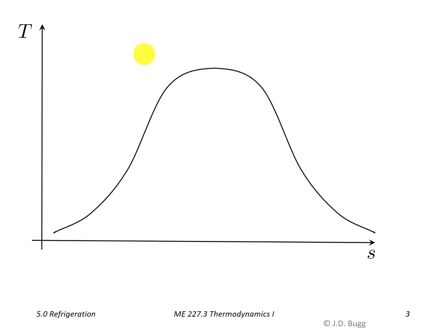In addition to looking at a Carnot cycle, we're going to be looking at a working fluid where we're in or near the liquid vapor region. So we're going to soon take our Carnot cycle and put it on this set of TS coordinates, and notice that I have a saturated liquid and saturated vapor lines already drawn on here. So we're going to be operating a Carnot cycle in the liquid vapor region.